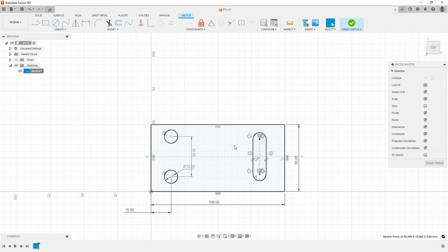There are still a few things you should pay attention to. We can still move the slot freely, and the color of the slot is still blue. This means that the sketch and slot are not fully defined. Only the rectangle geometry is fully defined, that is fully dimensioned and fully constrained. A rectangle has specific dimensions and a position relative to the coordinate system, and in the case of a slot and circle geometry, we don't have that yet. Let's deal with the slot.